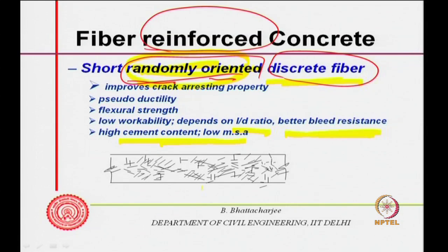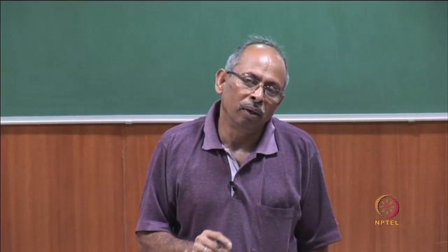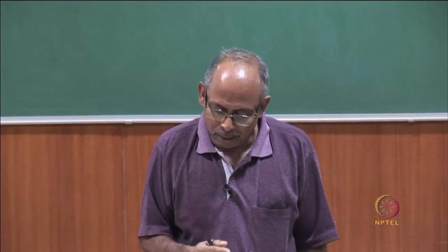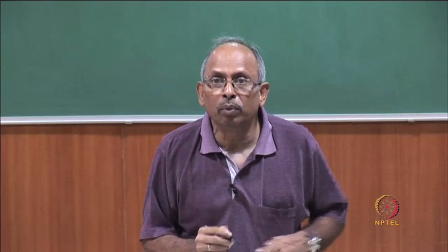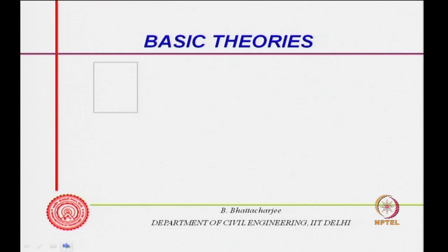So, let us say this is your concrete, and you have discrete fibers like this. When the crack comes, they will actually bridge the crack, and that is how they provide crack arrestation property. So, that is the understanding of the utility of the fiber, or where fiber improves. We can now look into some details, but before that we can quickly look into some theories which we will discuss a little bit today.